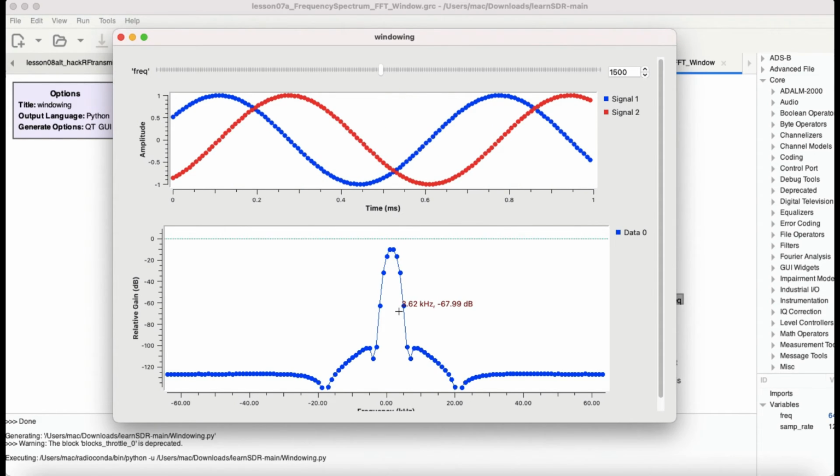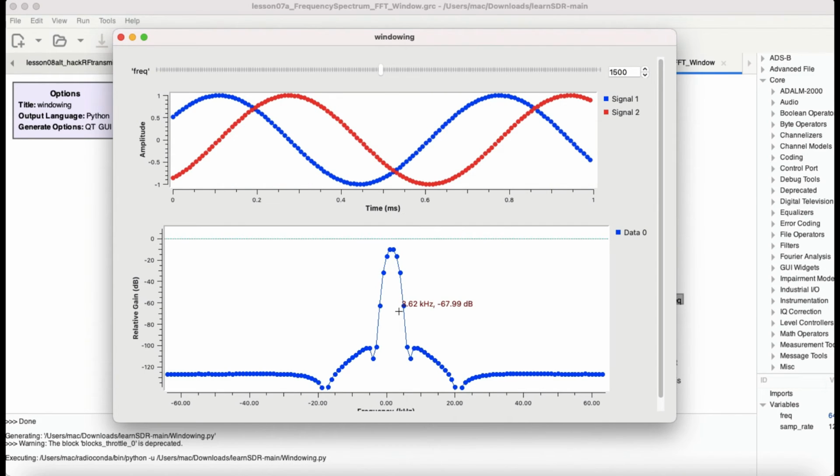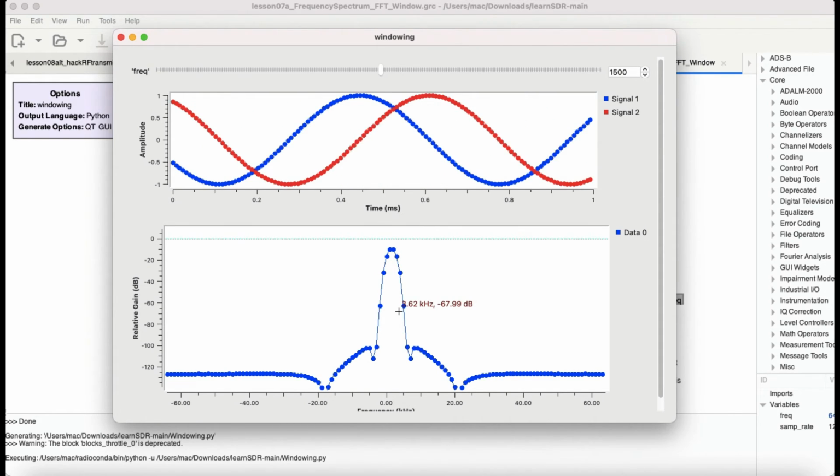If the signal is quite broadband, if your signal is quite flat, which means it's a uniform signal that contains a lot of frequencies, then use no window, which means a rectangular window. Basically, think of windowing like this: you have a signal, and you're multiplying it by another signal. Most of the time, when you think of a rectangular window, it's easy to understand.